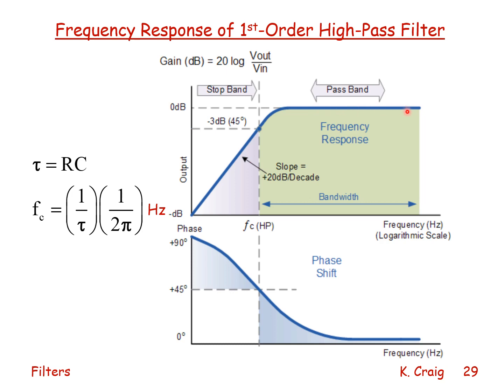This is the pass band. This is the stop band. Slope is plus 20 dB per decade in this region. At the break point, the phase angle is now plus 45 degrees. The output leads the input by 45 degrees. So these are my Bode plots, my frequency response plots. Amplitude ratio versus frequency, phase angle versus frequency.